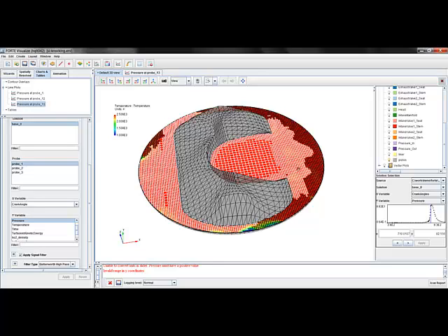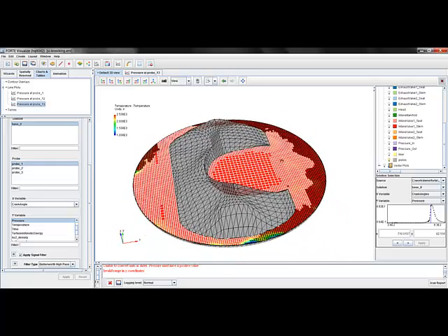What you see here is a cut plane through the cylinder, just below the head through the piston here. The white and black grid lines, where they intersect, show where the flame front currently sits. And the contour map you see here is for temperature. So what we should see ahead of this flame front is cool gas. So that would be the end gas. But in this case, we see that the end gas is already auto-ignited ahead of the flame front.